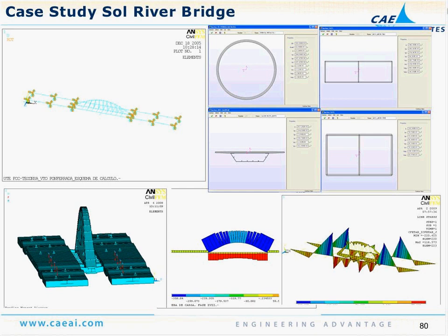The box sections are modeled with the box, and some of those are composite sections, a combination of steel and concrete, or a concrete deck and a steel underlying framework. A construction sequence simulation was used to develop the fact that the concrete would be poured stress-free after the steel box had already been developed.